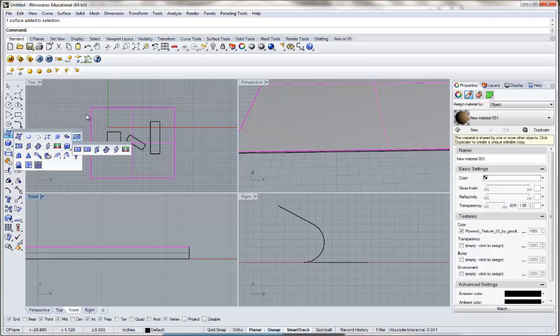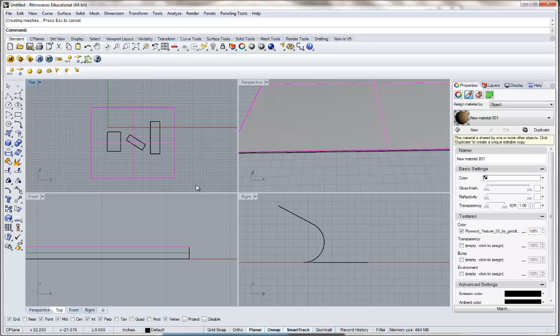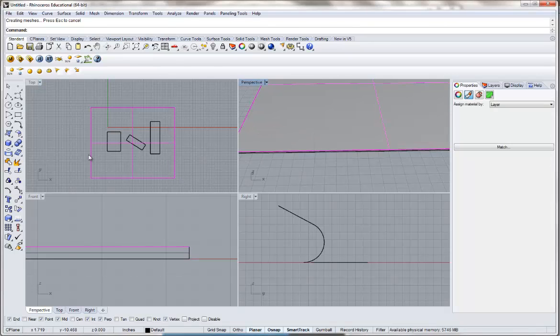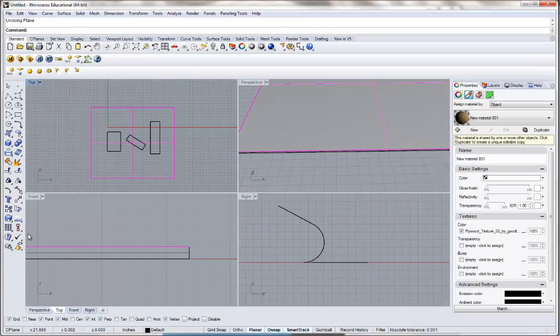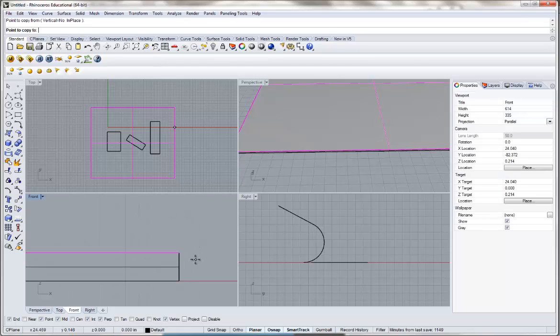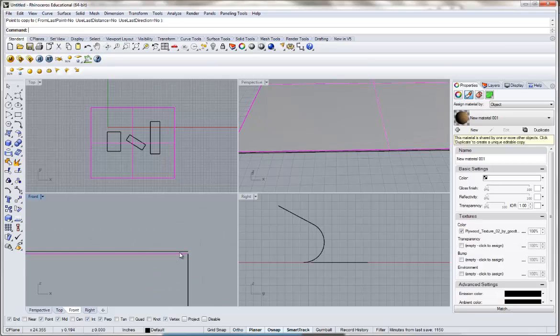So I'm going to go ahead and draw another plane here right on top of this. I'm not sure which one's going to be on top here, actually, so I'm going to not do that. I'm just going to take this and copy it up. And you only need to copy that up like 1/1000th of an inch for the modeling software. So 0.001. Something infinitesimally small, so that you can zoom way, way, way in to get it. Okay? So then we can come over here and set our materials.